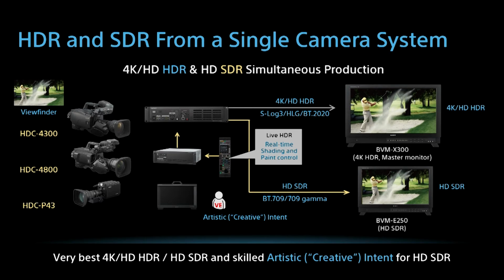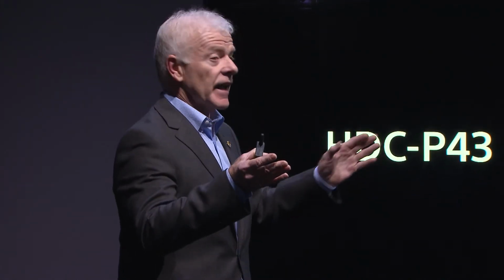When you turn on the cameras, the HDR path and the SDR path have the equal gain. As the operator opens the iris and starts increasing the brightness of the HDR path, the pictures look very good. But then you may compromise, you're going to clip the SDR signal. It is at that point that we introduce differential gain and attenuate the value of the light going into the SDR path,